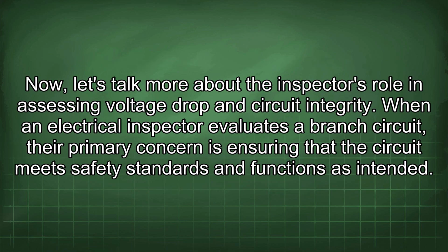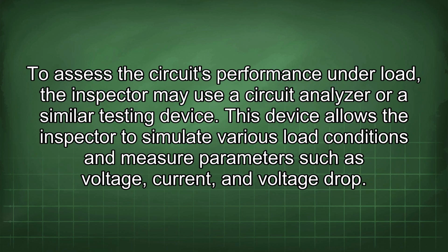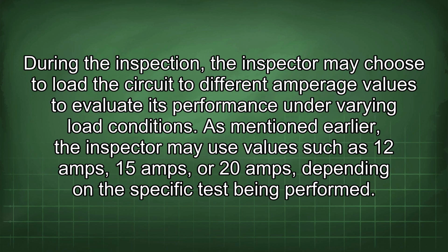Now let's talk more about the inspector's role in assessing voltage drop and circuit integrity. When an electrical inspector evaluates a branch circuit, their primary concern is ensuring that the circuit meets safety standards and functions as intended. To assess the circuit's performance under load, the inspector may use a circuit analyzer or a similar testing device. This device allows the inspector to simulate various load conditions and measure parameters such as voltage, current, and voltage drop. During the inspection, the inspector may choose to load the circuit to different amperage values to evaluate its performance under varying load conditions.